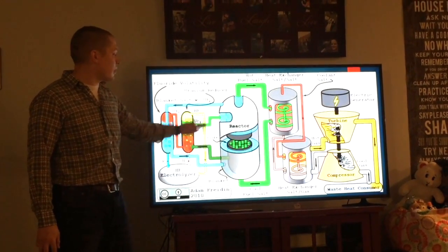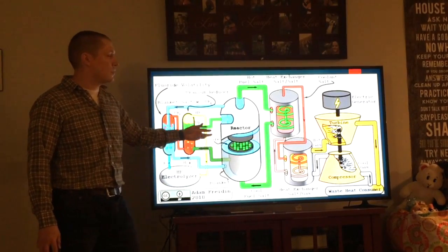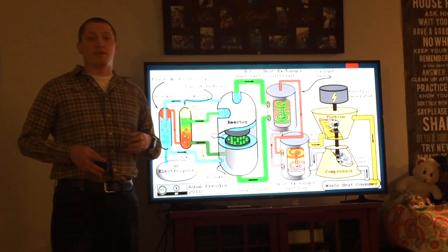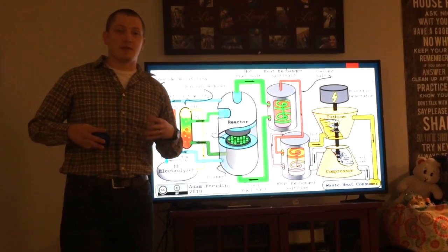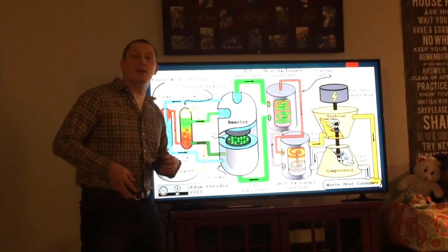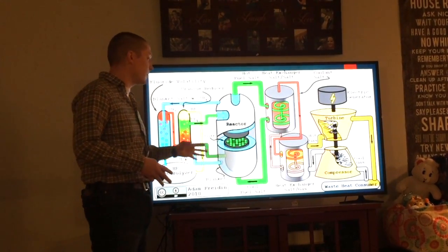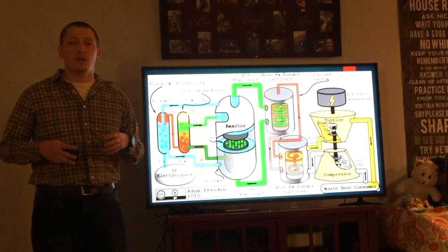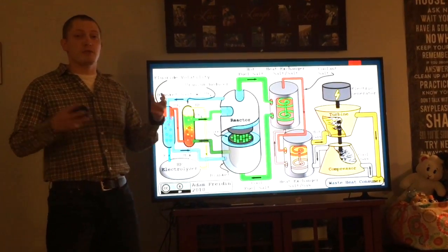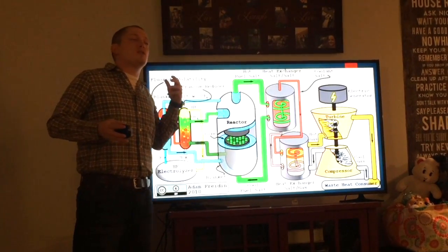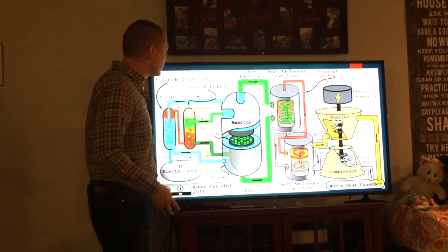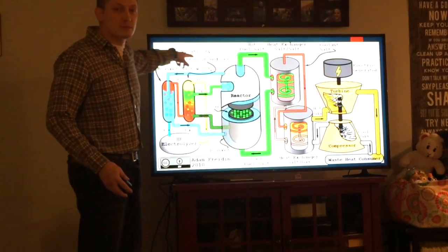Now, in the reactor core, that's where most of our fissioning occurs. So we have lots of fission, we have lots of neutrons flying around. The thorium blanket outside of this fuel salt is absorbing any of these neutrons that come to it. And then when it absorbs the neutrons, what does it do? It gets changed into uranium-233. So this thorium blanket is also flowing continuously